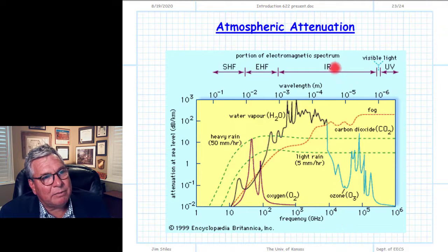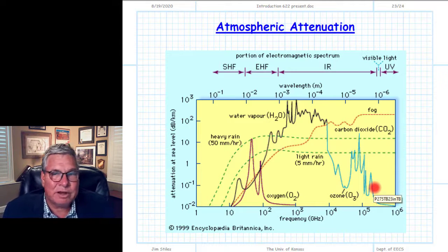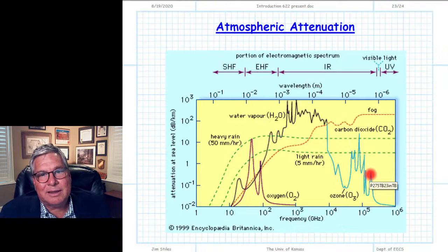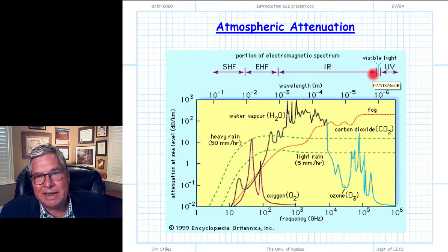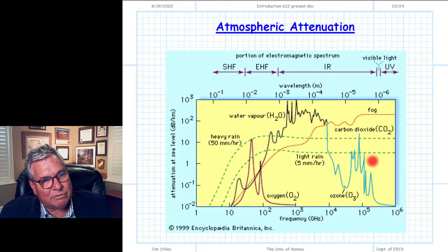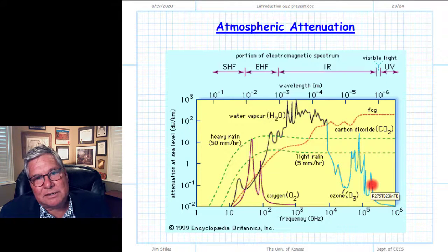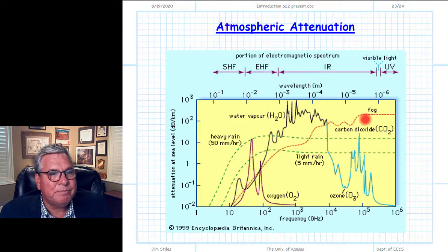Just below visible light, we have infrared, and notice there's a region just below it that is fairly clear. And so there are a lot of radios built at infrared. There are still propagation issues, but we use them, and primarily those radios go over a short distance, the distance between the couch and our TV, where we use infrared radios essentially as remote controls. They exist in this region just below the visible region, so we can't tell they're operating. They don't annoy us with their light, but the propagation through the atmosphere is still very good, and so they can become usable at that region.